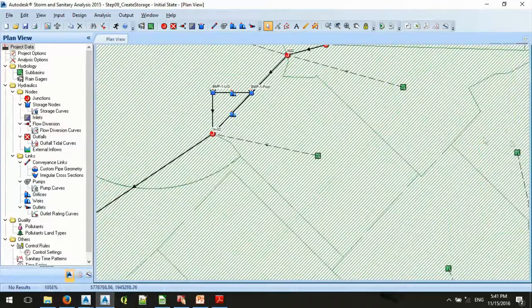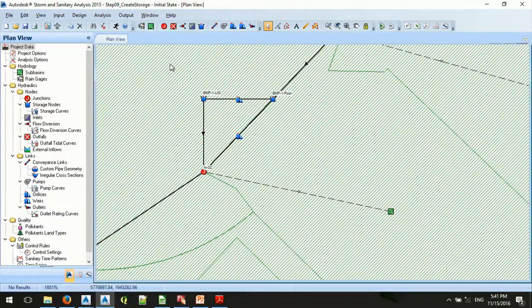This is a little bit experimental. This is meant to be a bioretention cell, also called a flow-through planter or a rain garden. And that has properties of surface storage and subsurface storage with a filtration media between. I was on the phone with Autodesk a lot about this. Apparently this is kind of an experimental thing, and there's no solid documentation on it yet, which I hope is one of the things this class will fill in. This method that we came up with is actually based on the work of Edward Houston in 2006 from Virginia Tech. He came up with this modeling technique and then validated it in the field.